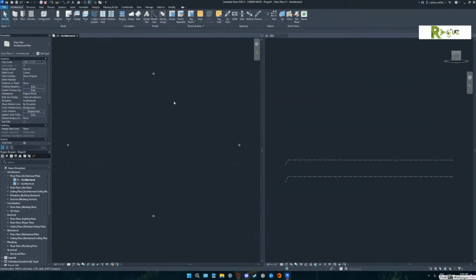This line will show up in every viewport that's a model viewport, as opposed to an annotation line or a drafting line that will only show up in the view that you're working in. I know that's a little bit, whew, what the heck did you just say? We will revisit that when we get to drafting objects. But what I'm wanting you to understand is those 4 elevation markers, what you want to do is try to draw your footprint of your building inside those 4 markers.